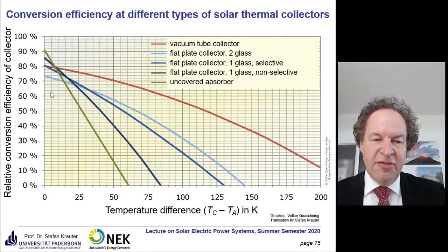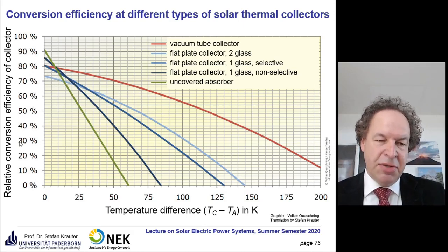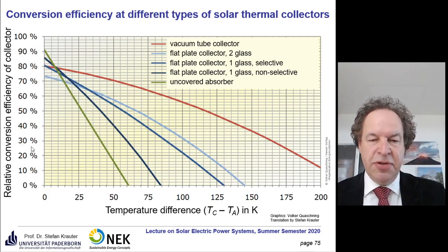While you have the highest efficiency here at the lowest temperature, you push a lot of water through the pipes, and there's not really a lot of time to heat up. But in general, the thermal losses are low, and therefore you have a high conversion efficiency. That explains this bit, at first sight a bit strange behavior of the relative conversion efficiencies.